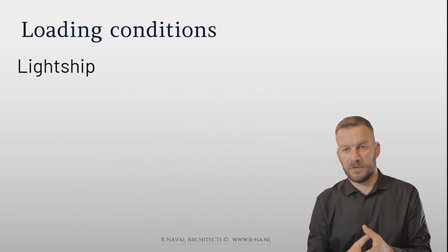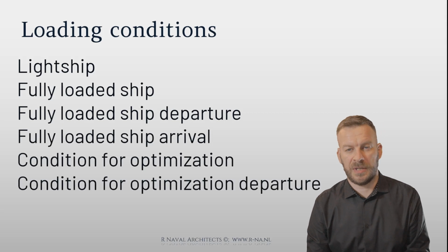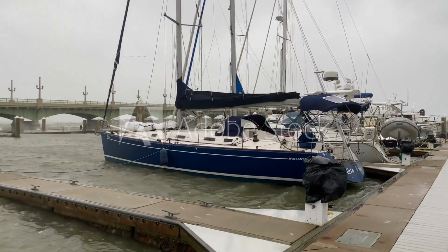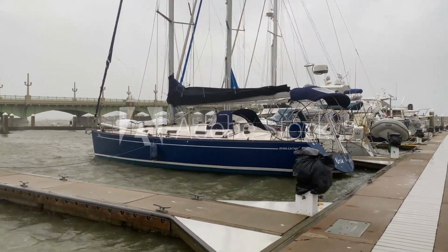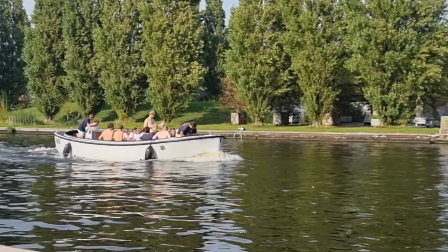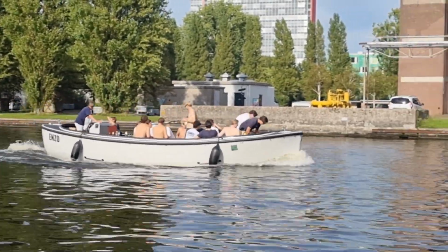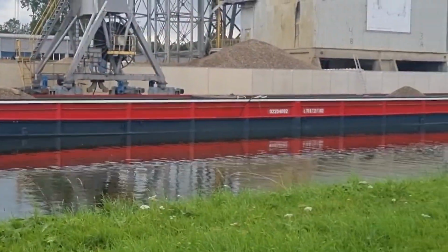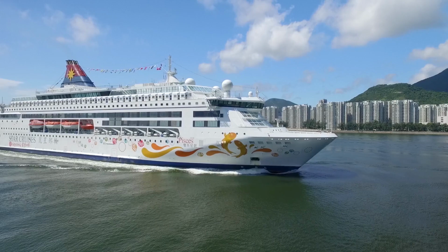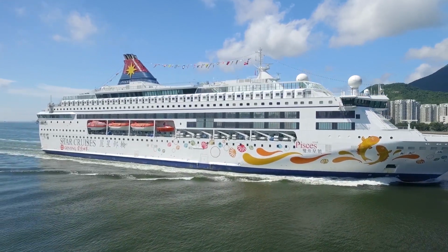In the life of a boat or ship, it doesn't matter, there are several conditions that are usual or most occurring. One is lightship, and that's when the boat is really just produced and staying still in the water without anything in it, just like you purchased it brand new and that's it. There is a full condition. That's when it's fully packed with fuel, water, cargo, provisions, food, everything, right? Your stuff, everything. And there are numerous conditions in between. One characteristic condition is a half load.